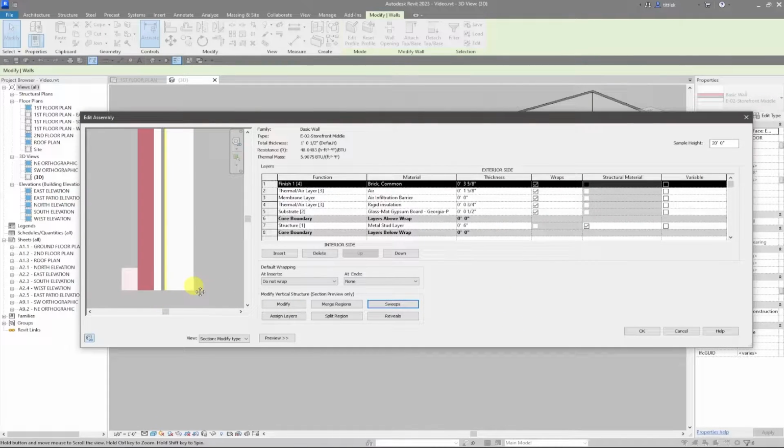And you can see that unlike our own profile that we created, this one seems to be flipping it to the opposite side of the wall. So its orientation is backwards. And that just happens sometimes. Whoever created this profile for this sweep just had a different idea of what was interior and what was exterior. So what we need to do is move this into the wall, and this sweep is 3 5/8 inch deep because it is a brick sweep, and our brick is 3 5/8. So we need to move this into the wall by 3 5/8 of an inch.